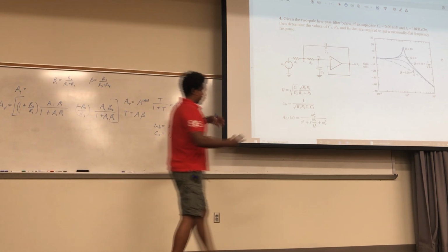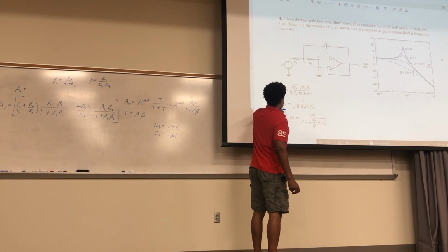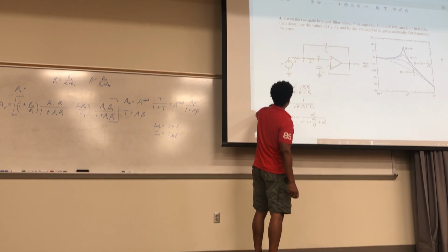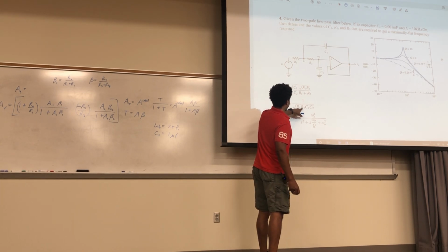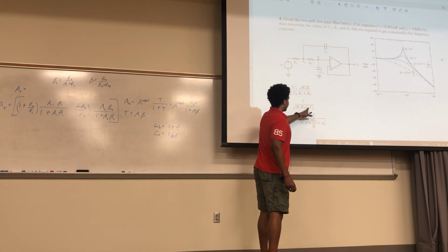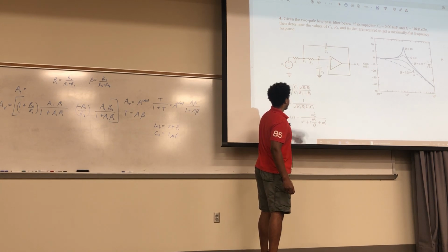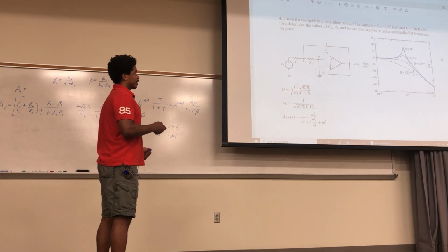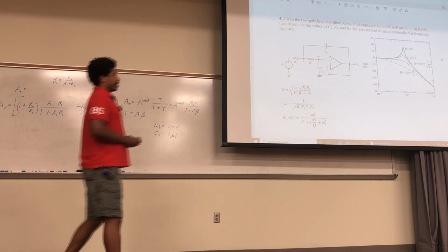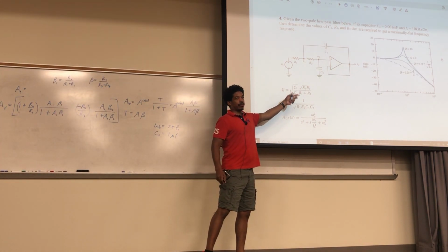So if you want to figure out the number, you put your 1 over square root of 2 here. You put your 10 kiloradians per second here, right? That'll be R1. That's 1 unknown. Your C2 is given to you. So you just have your R1 and C1 left over in this equation, R1 and C1 left over in this equation, and then you'd be able to solve for one or the other. What you would do is plug one equation into the other one for C1 or R1.